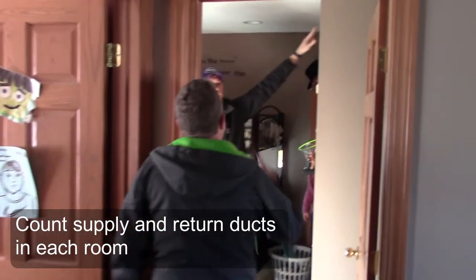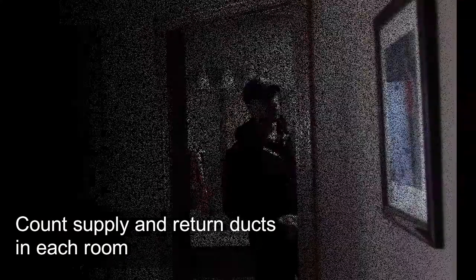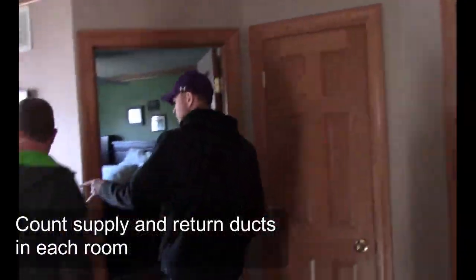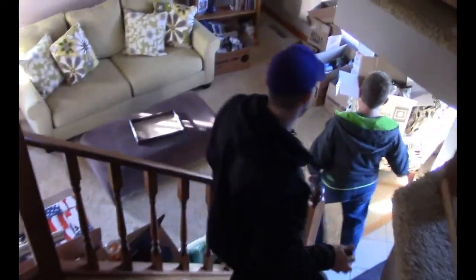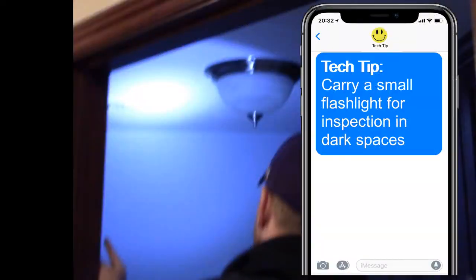Count all supply and return ducts in each room. Be consistent in your estimating. For example, start in the room furthest from the furnace and work your way through the house. Keep track of the ducts in each room. Here's a tech tip. Carry a small flashlight as you work. You can light up the hard to see areas.